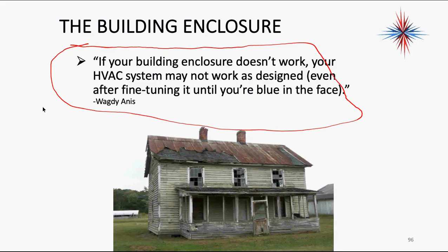You might go in there and see the system's working properly. You may be sorely tempted to make a small adjustment and say, okay, yeah, I adjusted it, let's see what happens. Well, then they're going to go look for the next company, because the problem might not be the equipment, and you might have to look at the house and do a quick heat load, which is why this is so important, and say it's not the equipment, it's the building. It's happened. I've seen it happen.